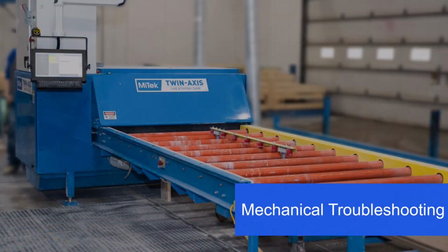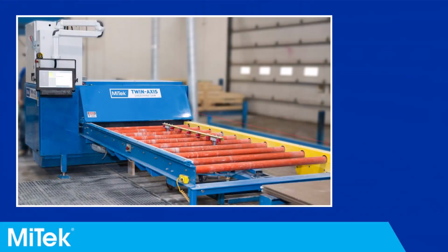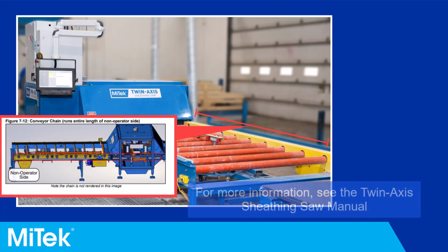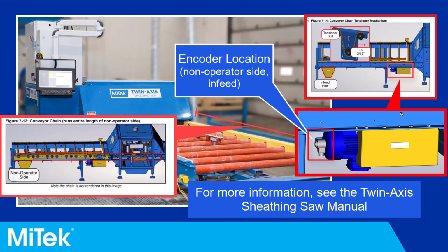Before performing a calibration, check the tension on the conveyor chain. The conveyor chain runs the entire length of the machine on the non-operator side. See the twin-axis sheathing saw manual for more information on adjusting the conveyor chain tension. Also check the encoder for damage or signs of slippage.